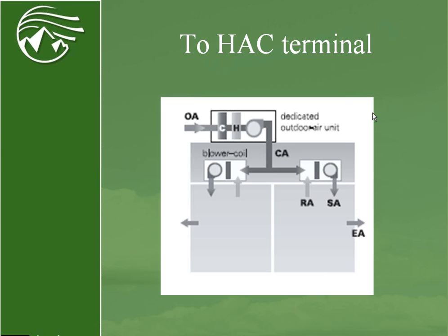Here you'd be mixing some air with return air, so you could actually modulate your outside air heating requirements. You can bring in some more, probably colder or untempered air if you're going to integrate that with your return air in your terminal units, but you'd have to accommodate that with the terminal units. They would have to be able to heat and cool that extra ventilation load. Or, as we mentioned, you could just fully temper the air and bring it into the terminal units and use that as your distribution device.